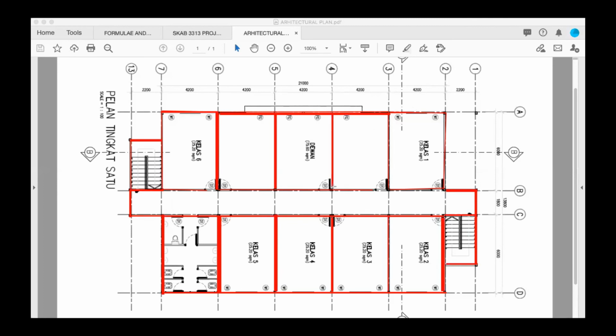It's better we put the beam here because the span is 4.2 here. But this beam will not support a wall, because this is the hall. You must remember that when you calculate the load, this one doesn't have a wall on it. These two don't, but here yes.